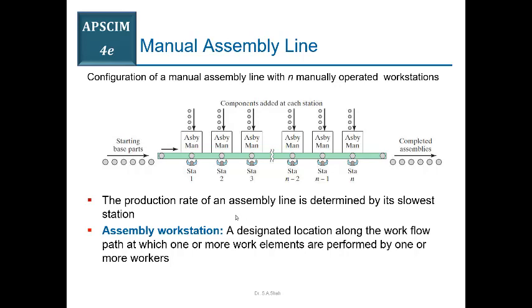The workstation with the largest processing time is the slowest workstation, meaning the one with the maximum machining time, and it will be the busiest workstation of the system.